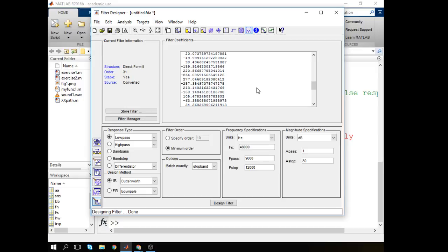How much does the smallest number matter here? Nada. But it still affects this system. When you are calculating it, it just increases the amount of calculation errors. So for that reason, we usually use second order sections on higher order systems.